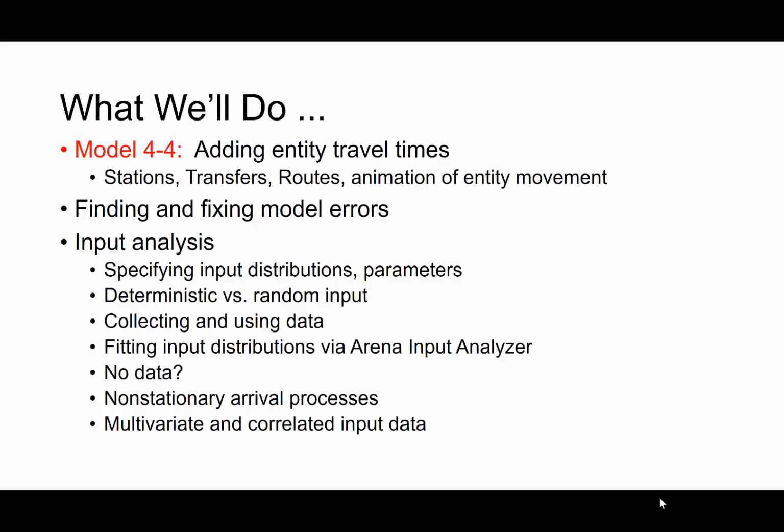We'll find and fix model errors and then do input analysis, such as specifying user input distributions for parameters, deterministic versus random input, collecting and using data, fitting input distributions via the ARENA Input Analyzer, what to do with no data, non-stationary arrival processes, and multivariate and correlated input data.